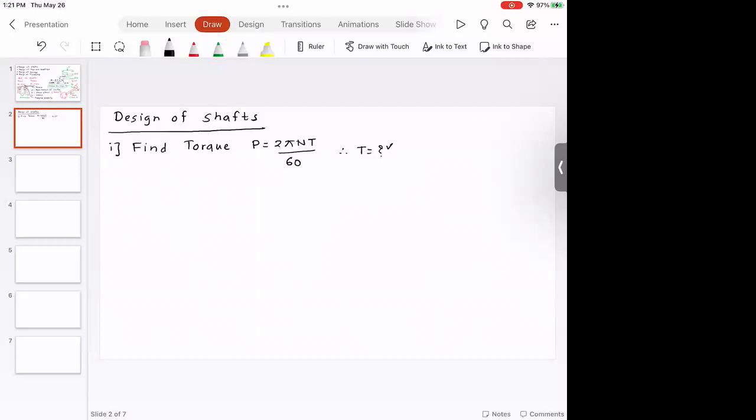Now, I don't know if you have seen this. Imagine you go to buy a treadmill. A treadmill that is for home use is different than the treadmill that they put for gym or commercial use. The treadmills that are designed to take abuse in the gym or in a student union or some other activity center where basically anyone can go and use it again and again are designed with higher factor of safety, better materials, and they are more rigid because the duty factor is significantly higher.